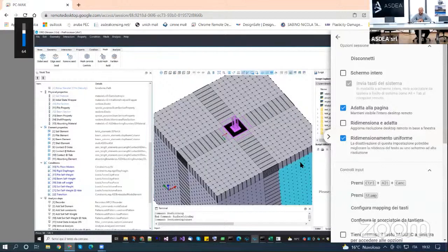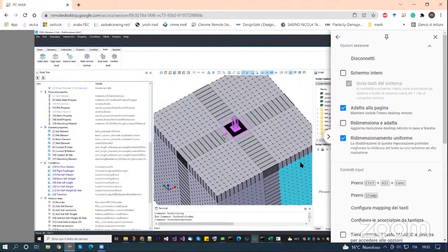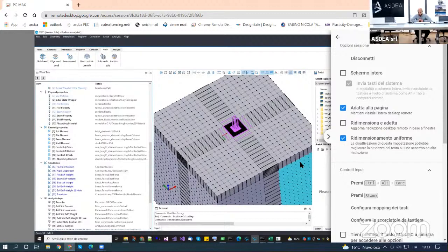If you were going to use an earthquake input, which has a variety of frequencies, then we should also care about the lowest frequency that we input in the model. So for an earthquake, to properly model one, we need a very, very large model if you want to model very low frequencies. But that's why, when I was doing this one with the Ricker wavelet, it's kind of a benchmark, so you understand what happens.